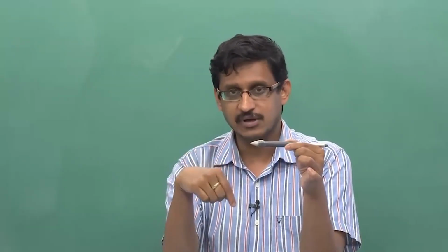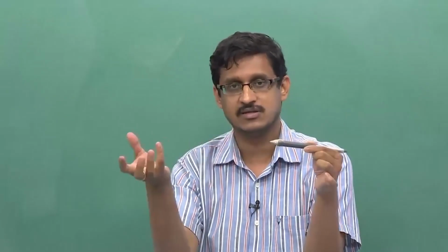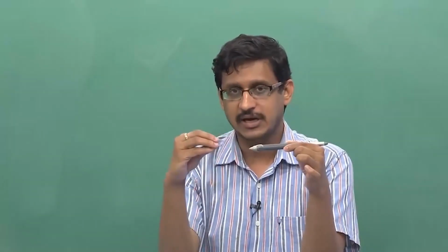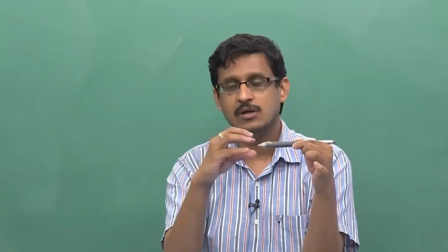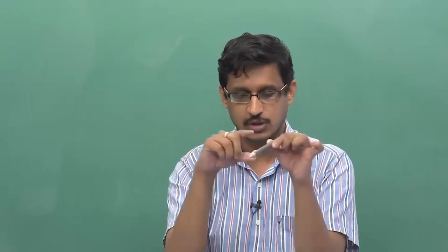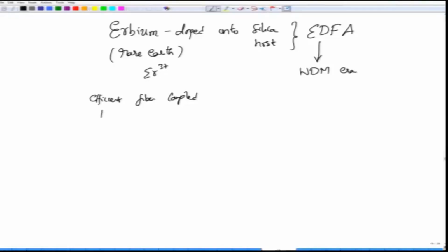The erbium doped fiber amplifier did not have such a problem, although there is a different kind of problem. This problem is largely mitigated because your input is fiber and the amplifier material is also in the fiber domain. Okay. So, it was a very efficient fiber coupled device, and more importantly it could amplify multiple wavelengths simultaneously.